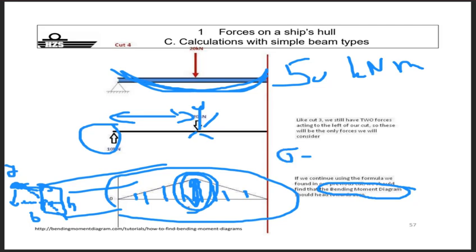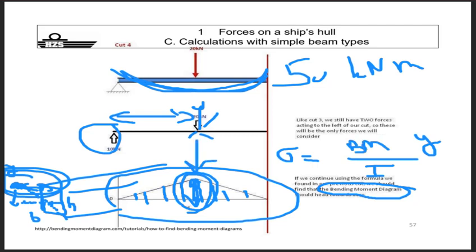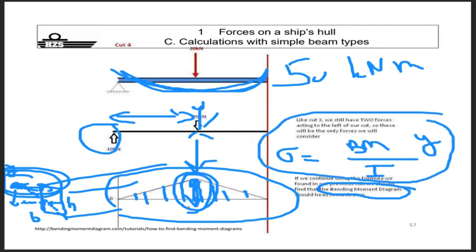What are the stresses at the location the furthest away from your neutral axis? Yeah, equals what? The resistance against bending we put downwards, and we put the bending moment at that spot, what you calculated here. And then you can calculate the value exactly of that stress level.